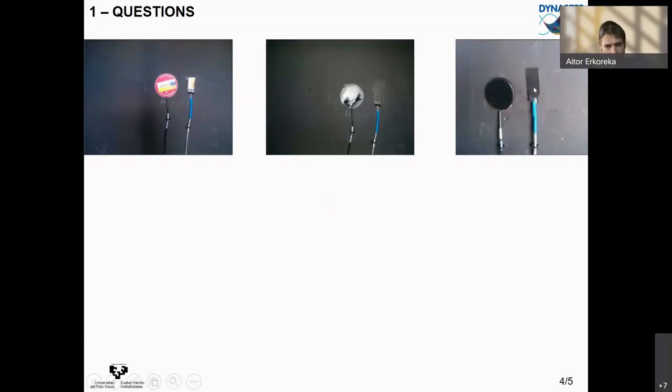Because this way, the surface and the sensor will have a similar emissivity, so they will behave in a similar way in the heat exchanges that occur on the surface of the real wall and of the temperature sensor. They will exchange heat by convection, and by long wave radiation and short wave radiation with the surroundings. The short wave radiation is actually the solar radiation.